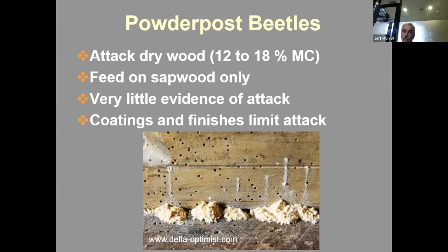They only attack sapwood, and they don't attack all sapwoods. They attack woods with more starch. So if you go to the Australian National Standard AS 5604, you'll see that there are rankings for powder post beetle susceptibility, or lyctid susceptibility, within that, which tell you what woods need protection and what woods don't. Coatings and finishes limit attack. So that's an easy way to do it if you're using finished wood.